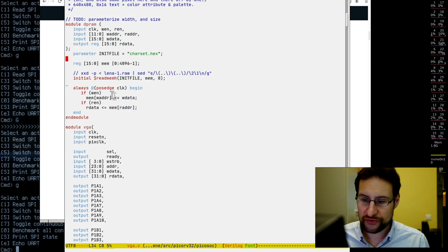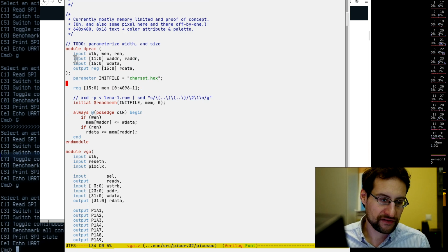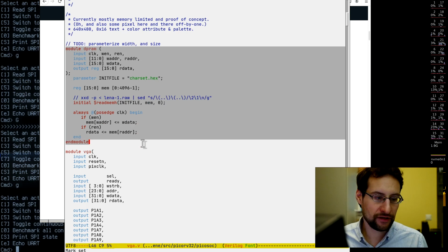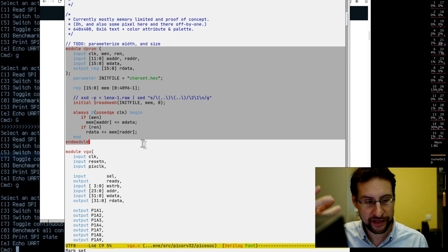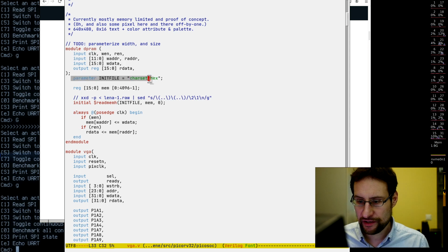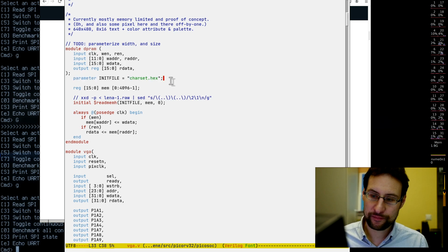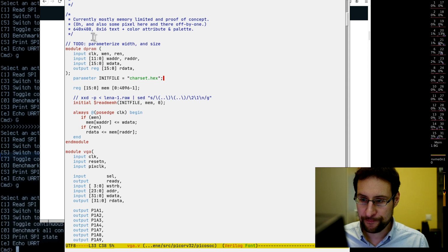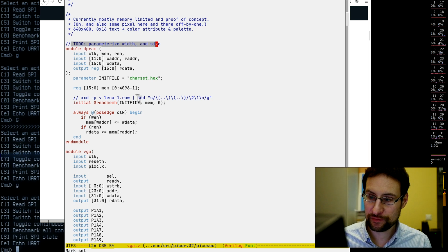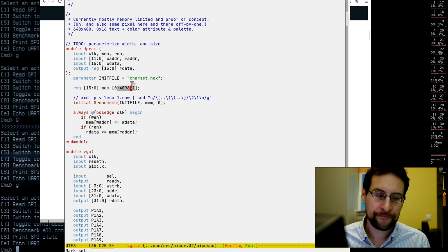If you want to see, we employed quite some fancy Verilog here. We define our module here for dual port memory, as we learned the hard way, to make this behavior analysis instantiate the logic cells using dual port memory. Also new since yesterday, I still have to further improve this. For example, theoretically I have here to parameterize the data width. Right now it's hard coded for 16-bit. It would be nice to have a parameter for width and size and not hard code this. That's a totally easy thing.